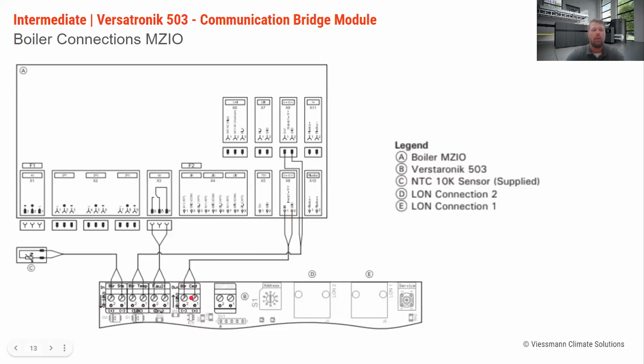And we do have to make sure that once we power this E-series boiler up, we do have to ensure that we go to address 1706, VDD 1706, and ensure that's where we turn on 0 to 10 volts. So we have to make sure that we go in there and turn it to a temperature demand, so that the boiler will respond to this 0 to 10 volt call that we are giving it.